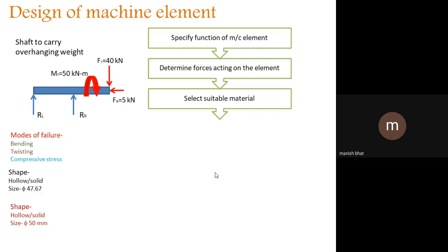Cast iron, we know, is brittle as compared to plain carbon steel. Brittle, it breaks easily. By hammering also it will break. But it is shock resisting, it is going to absorb vibration. So the beds of machines are designed using cast iron. So selection of material is again an important task in the design of machine elements.